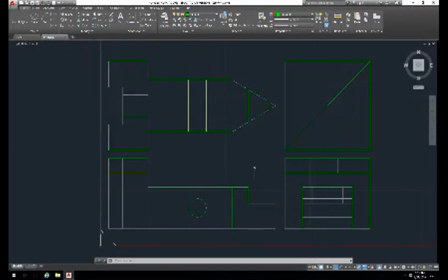And so you set up these defaults, and you can save them as a template and then open up the template. But one of the ways you can approach this is you can take a drawing that you've created, open it up, and then just erase everything and save it as a different file. The definitions for like the dimensions and whatever other definitions, they will be there.